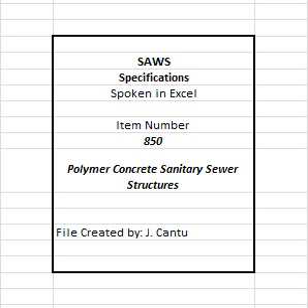H. Any structure excavated for repairs or excavated for tie-in, shall be backfilled with minimum of 12 inches thickness of flowable fill to 1 foot below the top of the cone section to allow for the concrete ring encasement. I. The contractor also has the option of backfilling with approved secondary materials, subject to the provisions of specification item number 804, excavation, trenching and backfill.